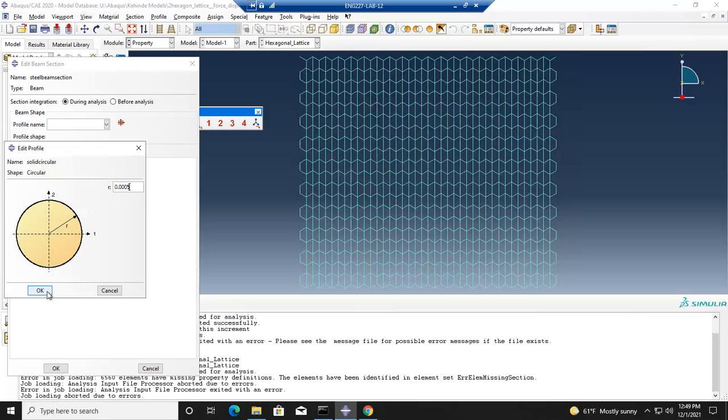Okay, you got what I'm saying? That is SI unit. Right. So if we are choosing SI unit, we need to make sure all our quantities are in SI units. The elastic moduli, loads, all the lengths are in meters. So if you change anything there, then it will all get thrown off. You got what I'm saying, right? In Abaqus itself, there is no unit, so it will not do any unit conversion for us. Okay.